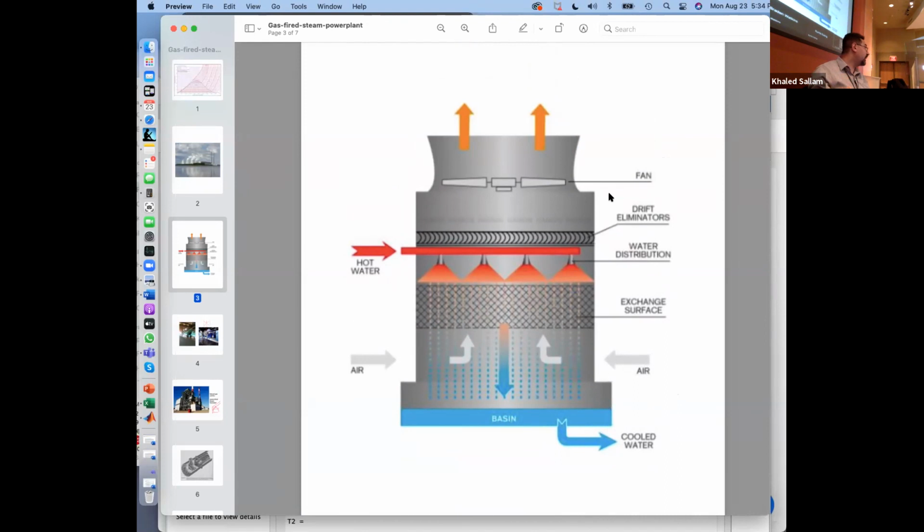And the Q dot rejected that the power plant is requiring you to take becomes m dot h_fg. So you can calculate how much steam is coming by just saying Q dot rejected. If this power plant is 1 megawatt, no, it's not 1 megawatt, it's 1 gigawatt. If I have a 1 gigawatt power plant and I have 40% efficiency, how much is Q rejected?